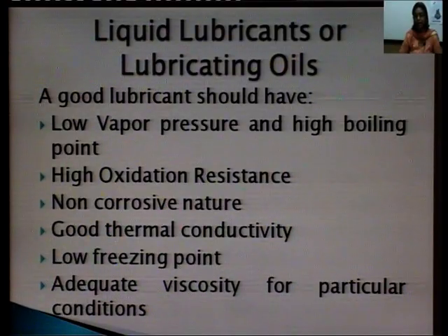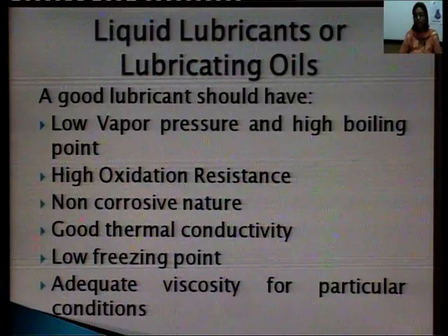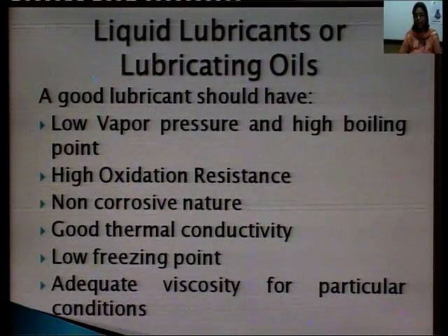Then is adequate viscosity for particular conditions. That means the liquid lubricants should flow properly even at higher temperatures and even at lower temperatures. Their viscosity should not change appreciably with the change in temperature.